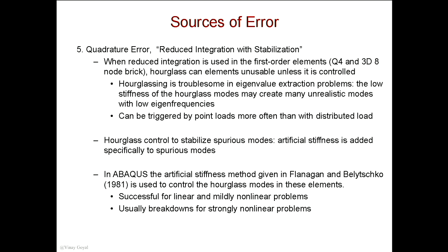And here I explain some limitations of hourglass control that could be of importance. So the only problem with full integration is that you might get shear lock, that's all? Yeah, typically. For full integration, shear locking tends to be the problem. And then for reduced integration, the issues are zero energy modes or spurious oscillations in the stresses. That can be an issue. Okay? Excellent. Any questions? Any questions here?